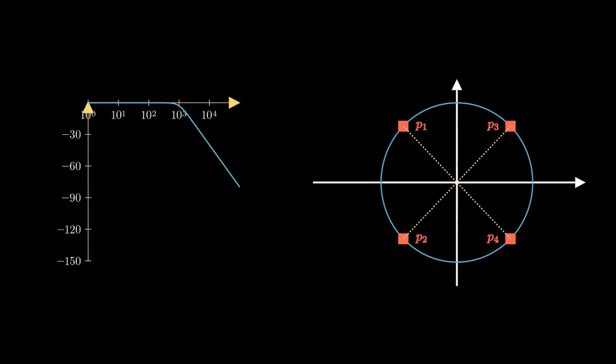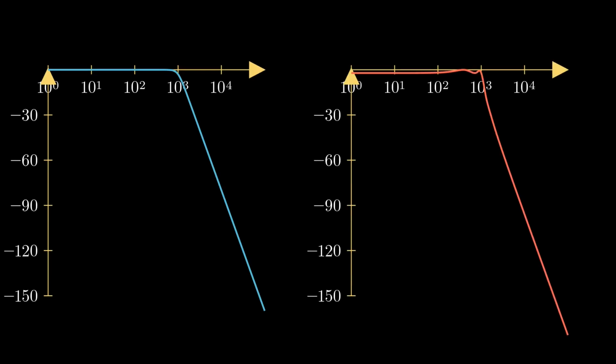This video will discuss its frequency response, pole locations, its transfer function, and how the transfer function affects the shape of the frequency response. The defining characteristic of a Butterworth filter is that its passband is designed to be as flat as possible, or in other words, maximally flat. In contrast, other filter types, such as Chebyshev filter, exhibit obvious ringing characteristics. It comes with a cost though, as the maximally flat filter means that the transition from passband to stopband is wide compared to filter types that have ringing characteristics.